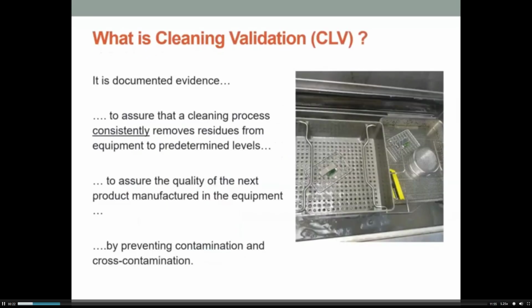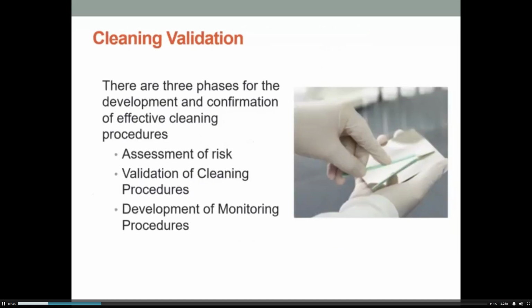What is cleaning validation? So you'll see in these presentations it's often called CLV. Cleaning validation is documented evidence to assure that a cleaning process consistently removes residues from equipment to a predetermined level, to assure the quality of the next product manufactured in the equipment by preventing contamination and cross-contamination. There are three phases for the development and confirmation of effective cleaning procedures. First is assessment of the risk. Second is validation of the cleaning procedure. And third is development of monitoring procedures.